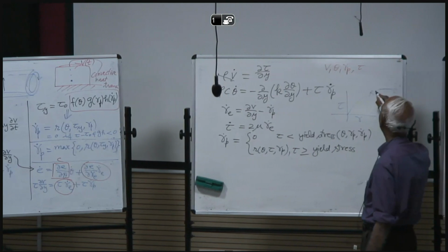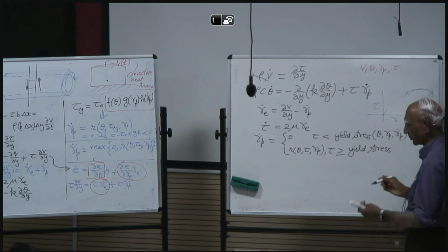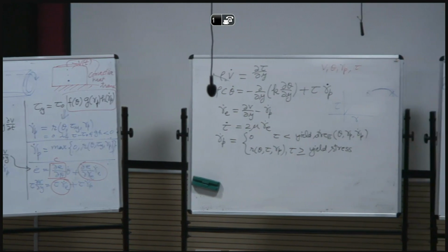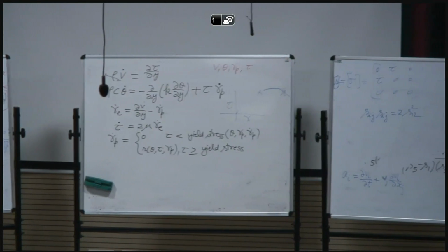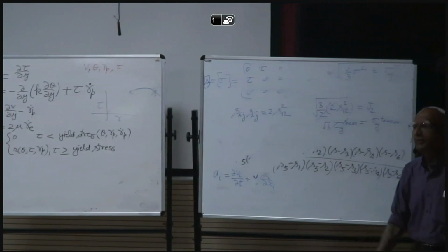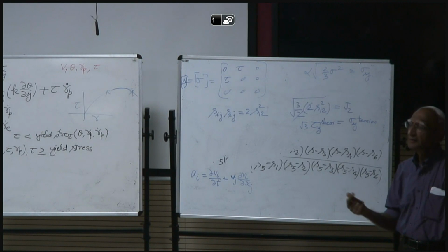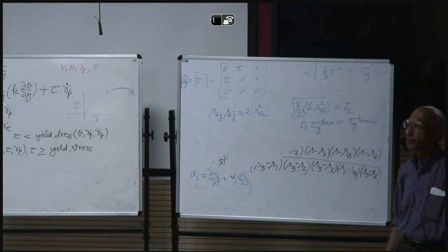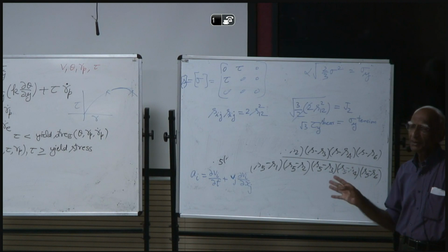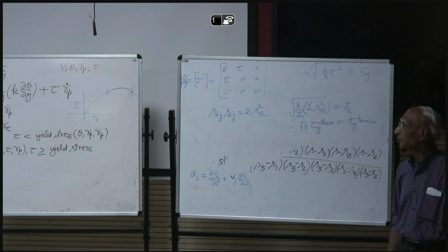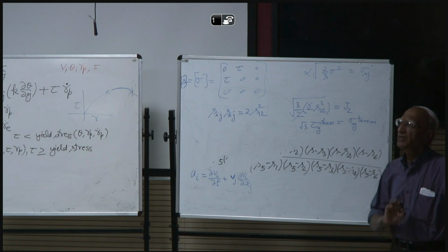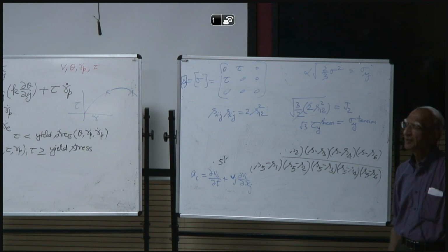It initiates when you are somewhere here, beyond that maximum in the stress curve. How far beyond you have to go, I will give you the answer. Once you are there and it starts rapidly deforming, only God can save you. There is no way, even if you unload it, there is very little chance that you will recover the sample intact.